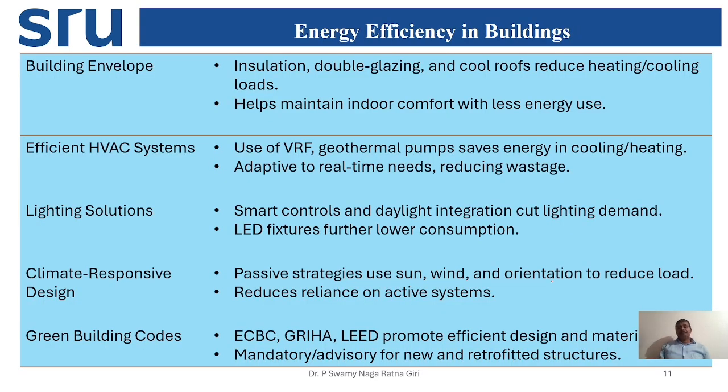Then we discuss the case studies, how energy efficiency in buildings is going to be developed. Let's discuss it point by point. We have the building envelope, where installation of double glazing and cool roofs reduces the heating and cooling system loads. It helps to maintain our indoor comfort, and less energy will be utilized.